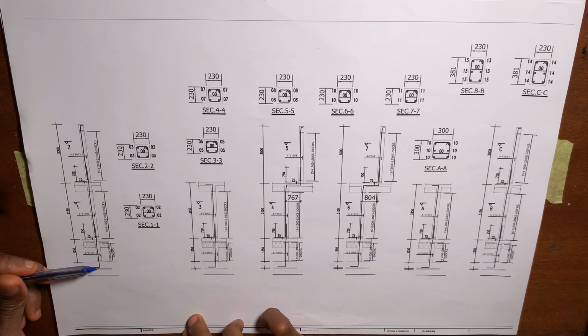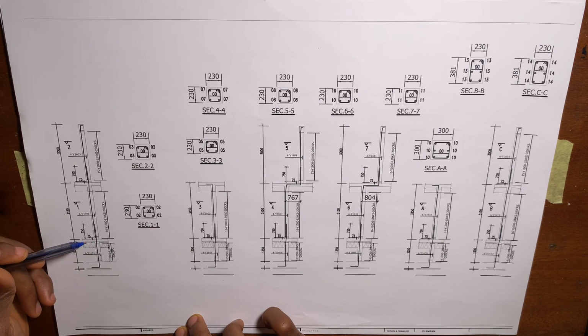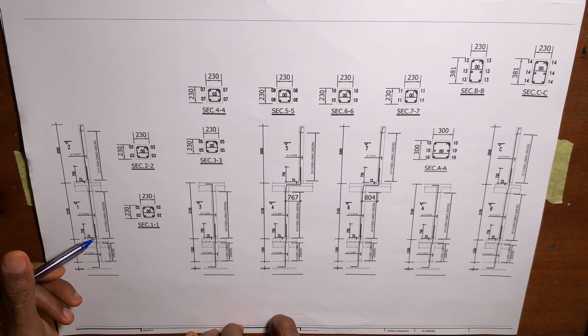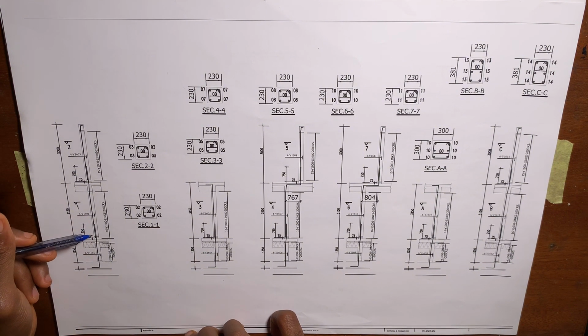So now if you look at this starter bar, there's a reason why it is called starter bar. You will see what I'm talking about. Now you can see that this thick line goes up, passes through the oversized concrete, and then there's an extra of 750 mm just on top of the oversized concrete. The purpose of this extra is so that the column for the ground floor, after the iron bender has already created the reinforcement for the column, the purpose of this extra is to give support to the reinforcement.